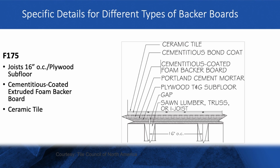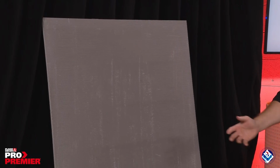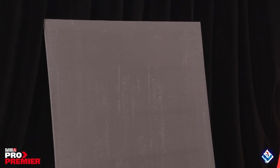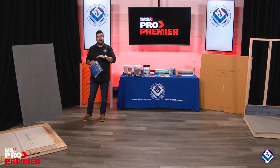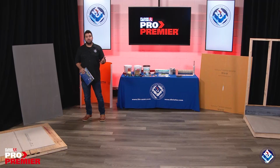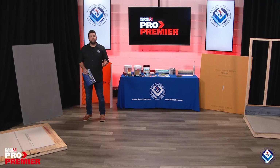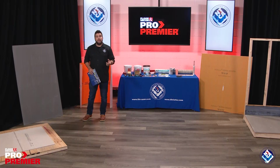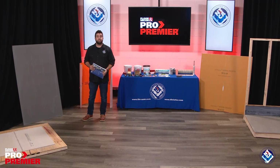Cementitious coated extruded foam backer board is slightly different in its installation. It requires that mortar be placed under the board to establish that supporting plane and eliminating voids. However, its ends and edges are fit tightly together and include the placement of a manufacturer's recommended sealant or banding in the panel's joints as they are installed, as well as over top of the fasteners, the heads of the fastener penetrations.